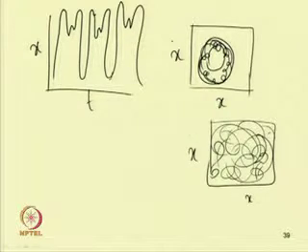To distinguish this from the time response, one can either plot the phase portrait or go for the Poincare section. In the Poincare section we have to sample the time response at regular intervals of time. For a periodic response, as we know the period of the system, we can sample the time response with the minimum period.